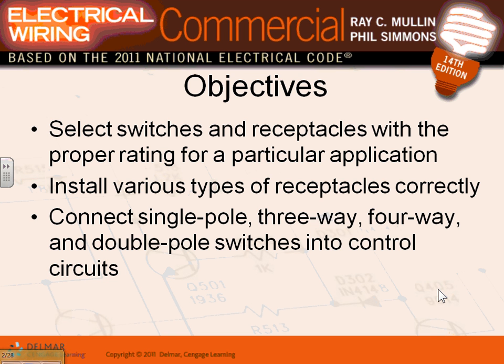So 6 single receptacles or 3 duplex receptacles. Where does it say that in the code? Nowhere. That's why people hire us. Thank God, because we are the ones who are supposed to come up with a criteria to lay out the receptacles in a commercial and non-dwelling building.